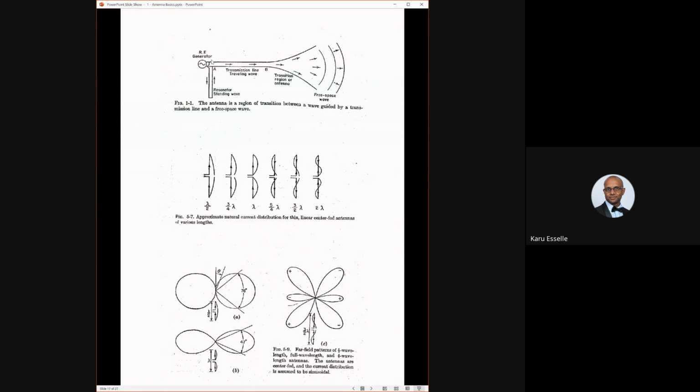So the dipole type antennas are very basic, and there's a history of that. Actually, there's an evolution of this. And this is a transmission line, right? It's a two-wire transmission line, like those two-wire lines we used to have to connect TV antennas, Yagi-Uda arrays on rooftops, to our TV sets. They're becoming increasingly redundant, though they may still be used in some areas of the world. The twin line transmission line.